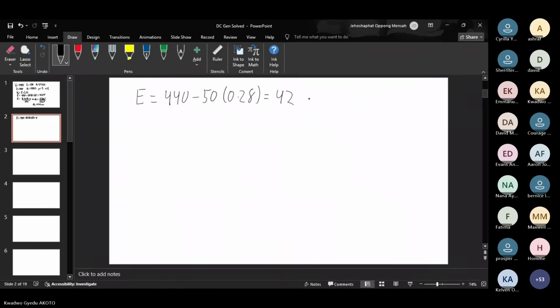So, right after our flux is reduced, we also know that E is equal to K phi omega m, right? So once our flux is reduced, there's going to be a reduction in our E before the speeding up can occur, right? Because if this reduces and this goes up, our E is going to remain constant.